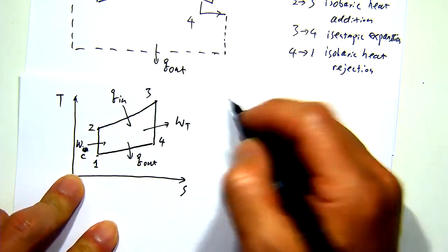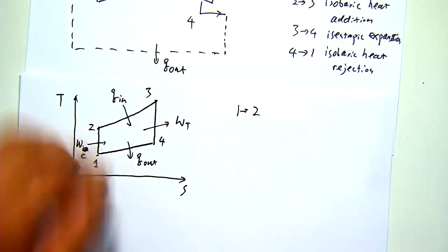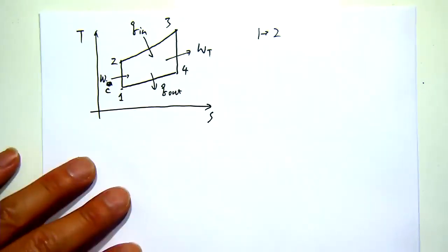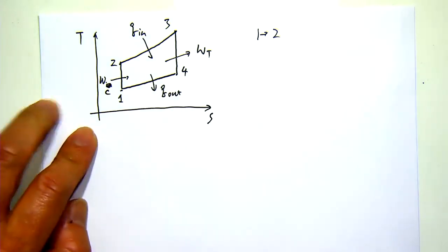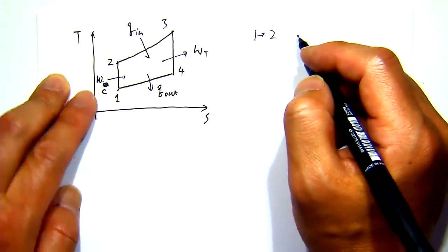So if we want to calculate the process 1 to 2, we are dealing with an ideal cycle. I should briefly define the ideal cycle. An ideal cycle is a reversible cycle, without any loss. There's no temperature loss, no heat loss, no pressure loss, which means no friction. And this process only has air, so air is the only working fluid. Even though fuel is burned in reality to heat up the temperature, we consider air the only working fluid, with heat just being added from the outside to the system. And also air has constant properties. Its Cp does not change with respect to temperature. All right, so if that's the case, from 1 to 2, we can figure out how much the compressor